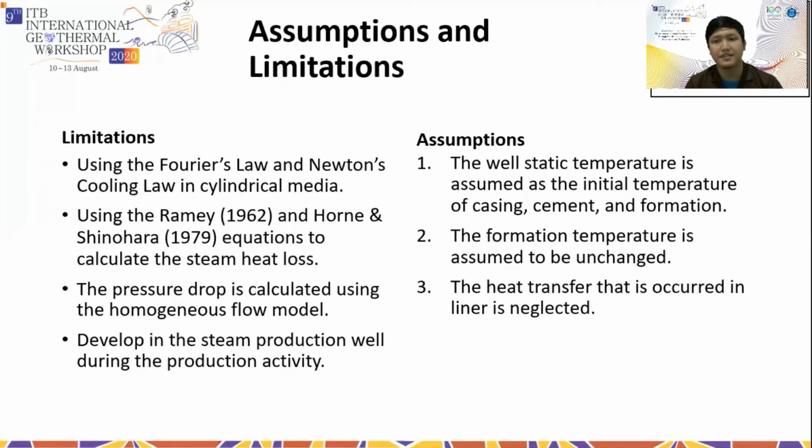Second, the formation temperature is assumed to be unchanged because the condition of heat transfer is a difference in temperature. In this research, the temperature difference is between the geothermal fluid and formation. And the last one is that the heat transfer that occurs in the liner is neglected because in the liner there are several production zones, and we need reservoir simulation to calculate the heat transfer in the liner.